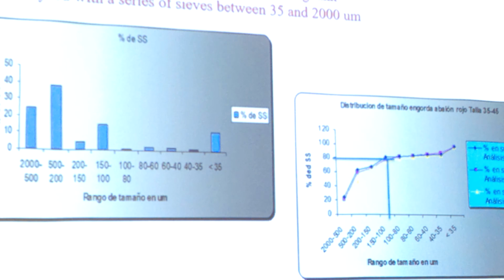Looking at the curve, it was quite easy, as a first approximation, to see which pore diameter for a screen device would be needed to remove a certain amount of solids. If we use a 500 micron device, we will only remove 20% of the solids. If we use 200 micron, we will remove 60%.